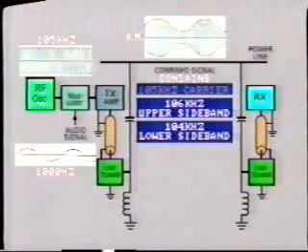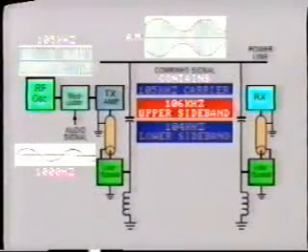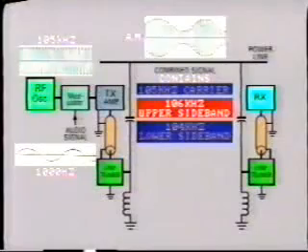Here, both the carrier signal and the lower sideband signal are suppressed in the transmitter, and only the upper sideband frequency is transmitted, 106 kilohertz in our example. The advantage is that it requires much less power to transmit the signal. And for this reason, portable communications equipment is usually single sideband, as there is a considerable saving in weight and size.